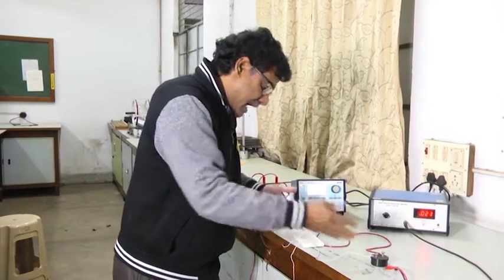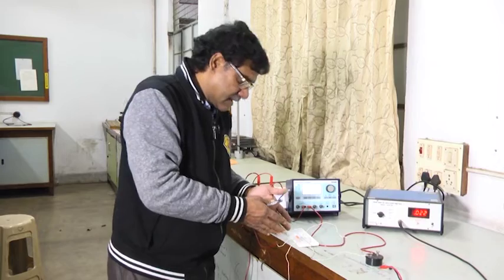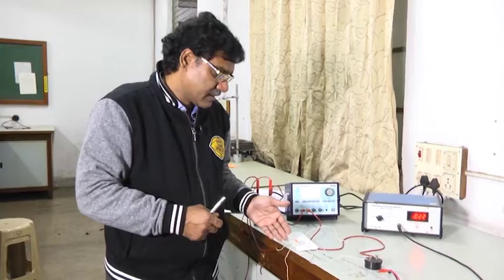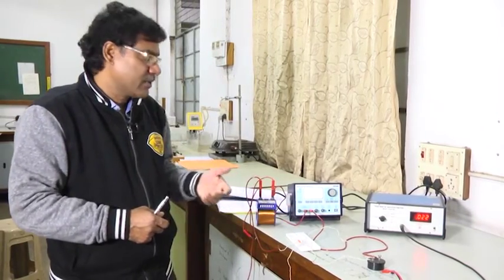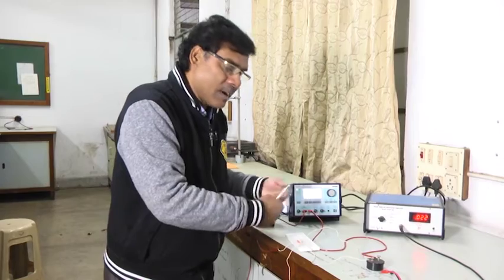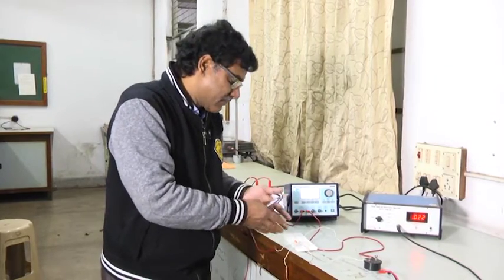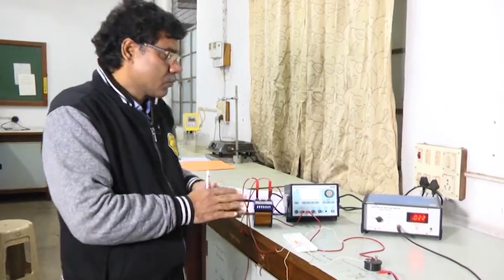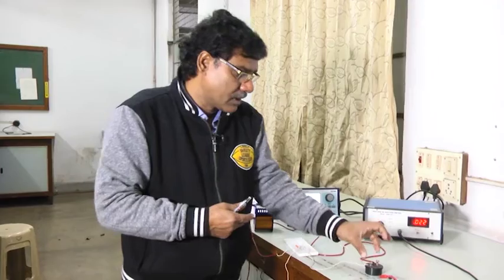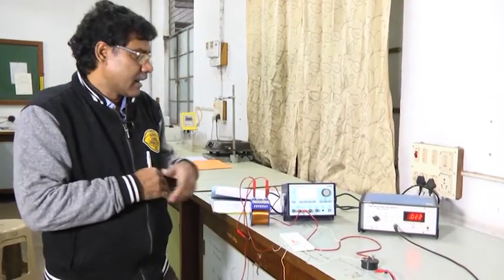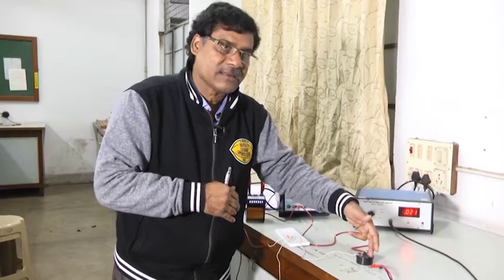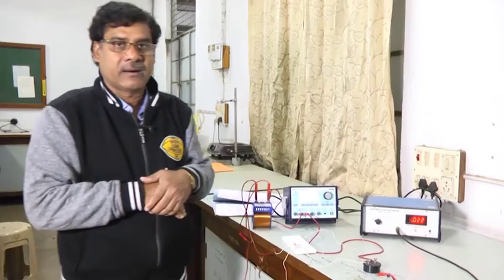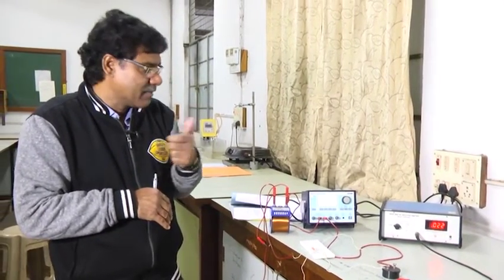If I measure the voltage across L and C, XL and XC will vary with the frequency, so all the time one has to find the reactances XL and XC, and that will be complicated. So, for knowing the current, we will measure the voltage across this resistance, and R is known to us, equal to 2. From there I will get the current, and that is the RMS value.